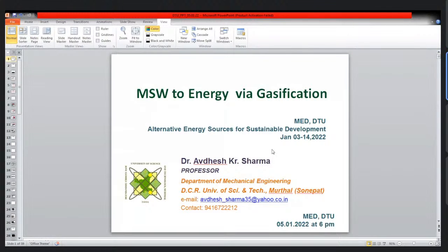Is there any minimum quantity of pilot diesel, sir? Yeah, I have told you. The recommended minimum quantity is 20%, the approved quantity. And sometimes it was observed that if the engine and gas quality are very good, it is almost eliminated, or only 5% or 10% is required to be injected. Otherwise, producer gas can substitute all the energy except this. 95% substitution may be possible.